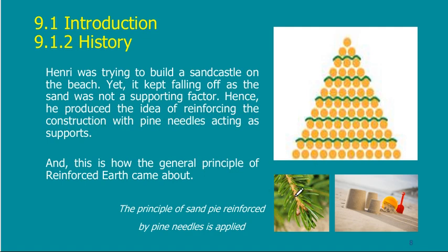He got these pine needles and added them inside the soil, whatever he constructed. Imagine that these are the soil particles, and I'm adding the pine needles in between. So what happened? He managed to build the sand castle very easily. And this is how the general principle of reinforced earth came about.